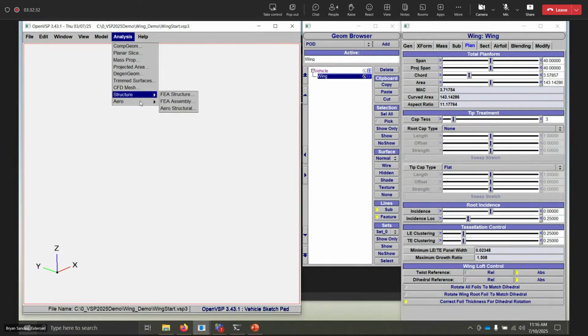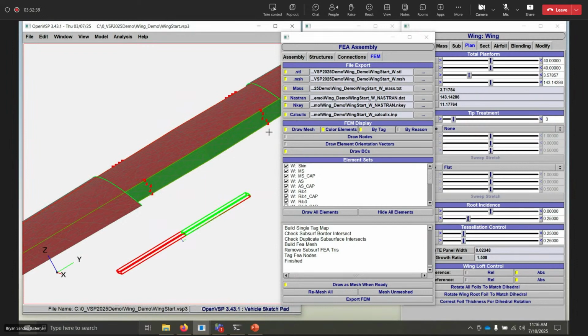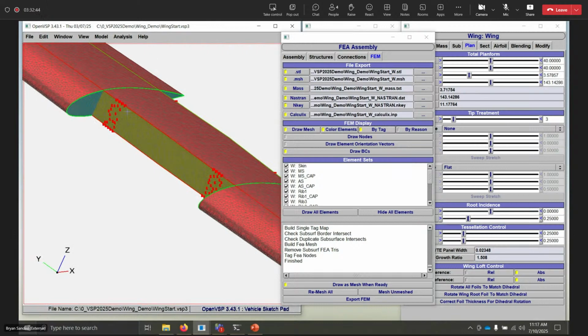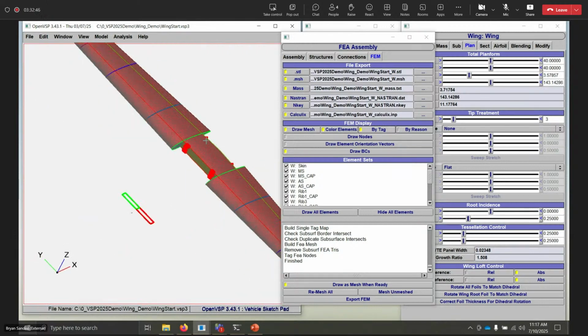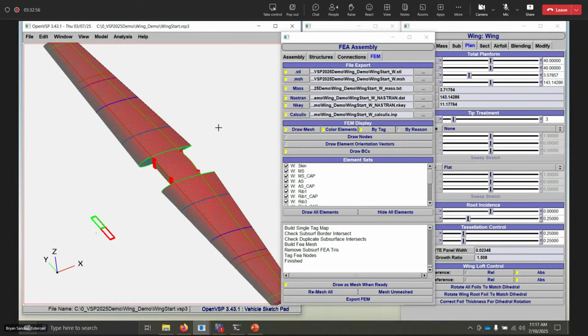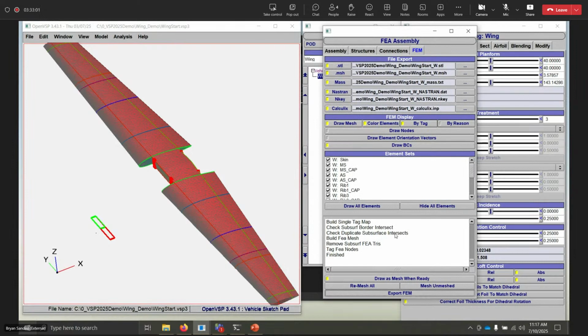Okay, go over here to our assembly, and there you go. So we have a strip of nodes there, strip of nodes there, more nodes on the front. Okay, so we have boundary conditions, we have a mesh. Let's take an opportunity here to inspect this outside of this tool. So we'll go ahead and we'll export the assembly. Assemblies only, right? So we'll export the assembly. Notice there is a mass here, so we can talk about that part.